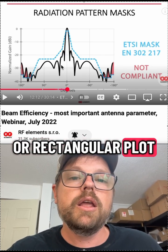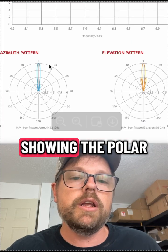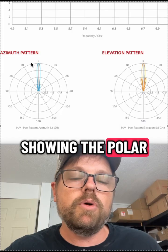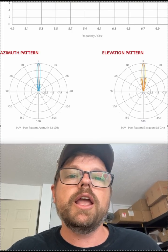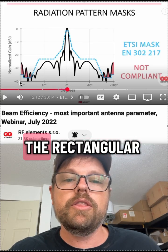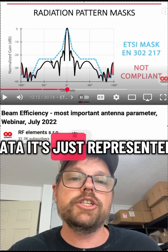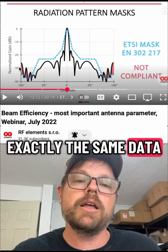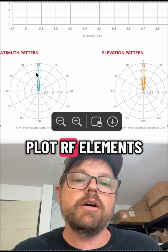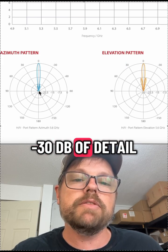Also, getting the level of detail from this, they call it an XY plot or a rectangular plot, versus the polar plot. So this is showing the polar plot representation of the antenna pattern. This is showing the rectangular representation. It's the same data. It's just represented differently, but it's not exactly the same data because the polar plot, RF Elements polar plots, only go to negative 30 dB of detail.